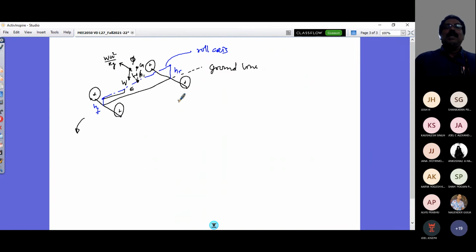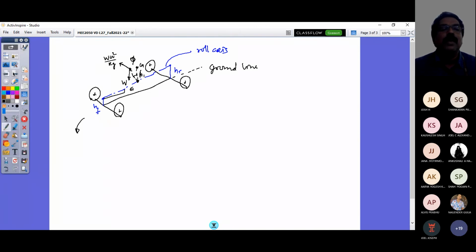So I would consider here that the roll of your vehicle is the same about this roll axis. So I have my front suspension, I have my rear suspension. There is a roll stiffness of the front suspension and the rear suspension. But the roll of your vehicle body is the same. So you would have your total roll now like this. So we had written how many equations, 6 equations, I suppose.